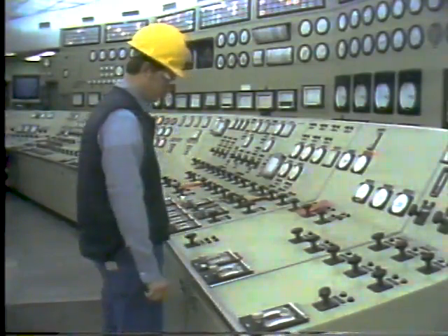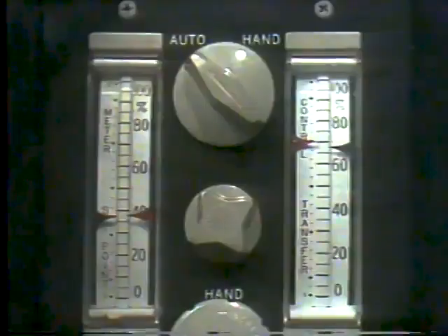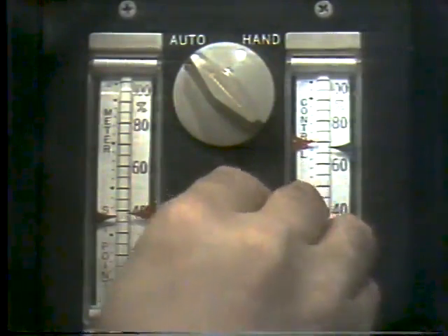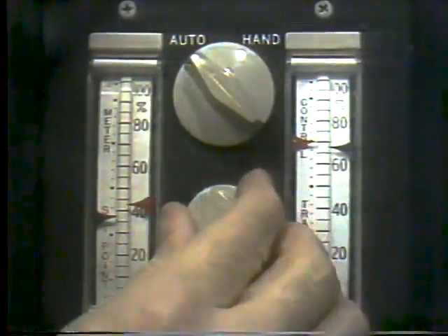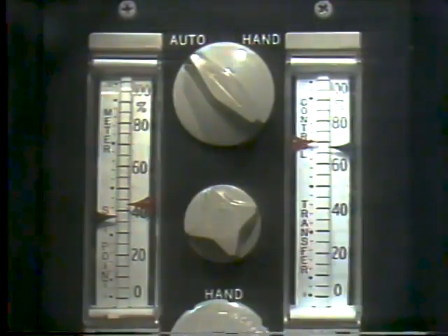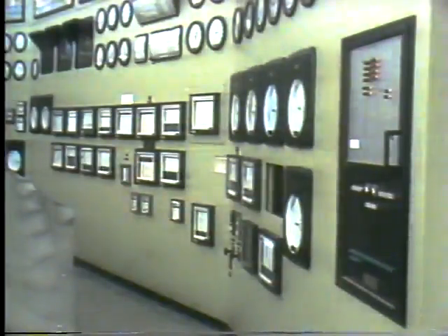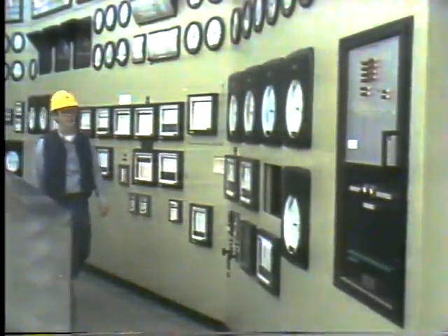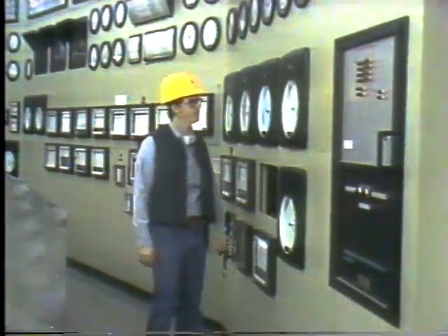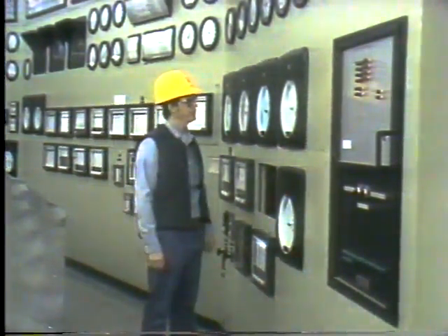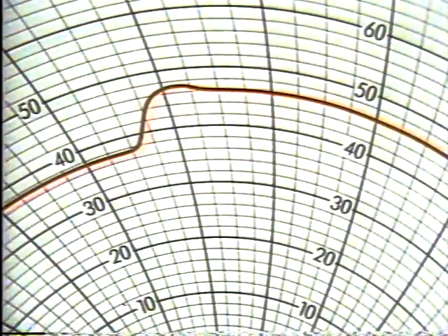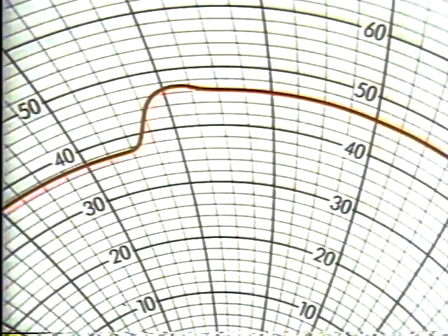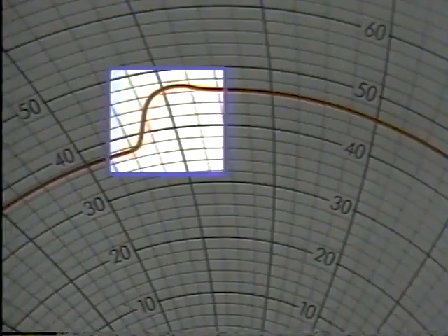After placing the system back into automatic, adjusting set point from 37.5% to 42.5%, and waiting for the system to stabilize, he analyzed the reaction curve. This is an illustration of what the technician saw. It indicates a low gain problem. There was almost no cycling.